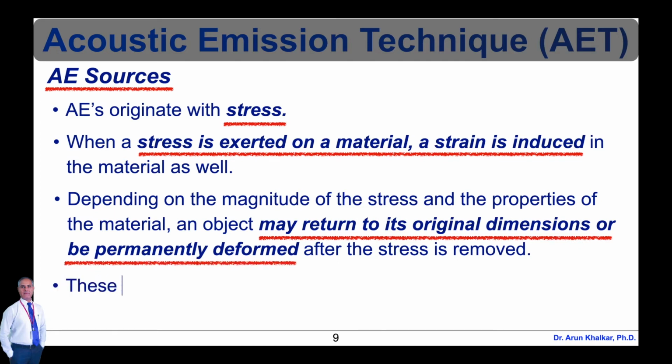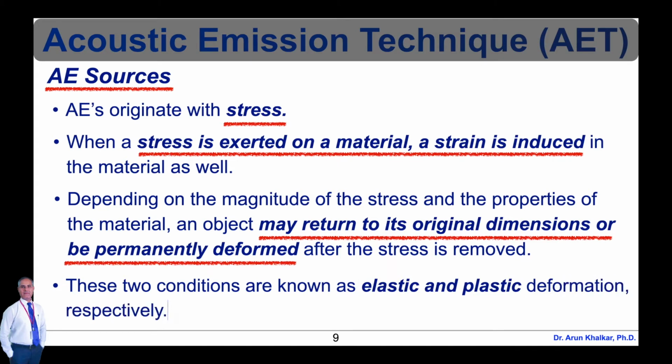The most detectable acoustic emissions take place when a loaded material undergoes plastic deformation or when a material is loaded at or near its yield stress. On the microscopic level, as plastic deformation occurs, atomic planes slip past each other through the movement of dislocations. These atomic scale deformations release energy in the form of elastic waves, which can be thought of as naturally generated ultrasound traveling through the object.